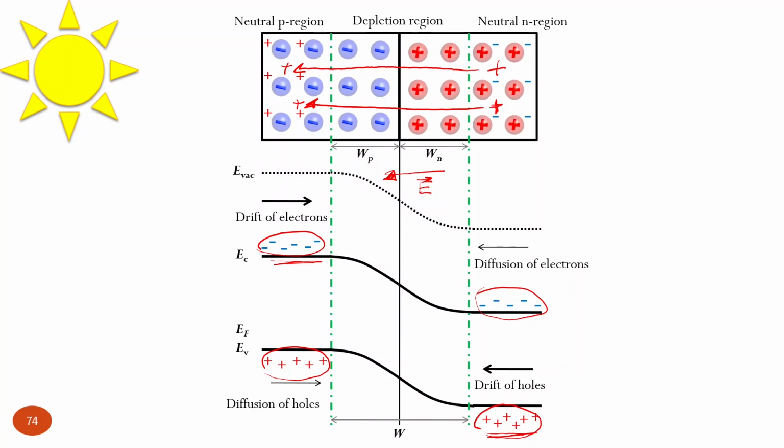It's not a minority charge carrier, which, as I told, when it diffuses, majority goes to another side, it becomes minority, and then it recombines very quickly because it's compensated immediately. Its electric charge is compensated within an extremely short interval of time, which is the Maxwell relaxation time.